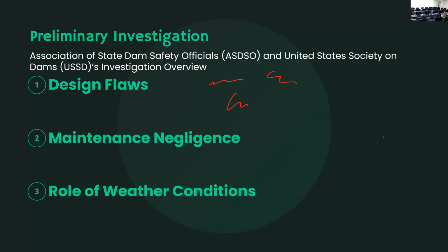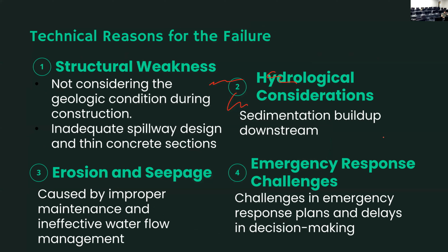The design flaws were that they built the dam considering that the soil underneath was hard rock, but that was not the case. We can see from the previous picture that it was easily erodible material down there, but they didn't make the necessary changes while constructing the dam.